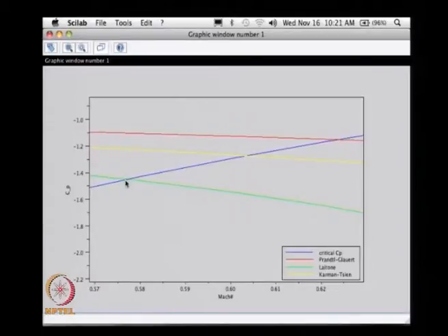So, any of these intersection points, okay. This is basically the critical coefficient of pressure, incompressible. So, with the suitable corrections, we get a usable coefficient of pressure. That will be given by the intersection of these curves, as you can see from here.